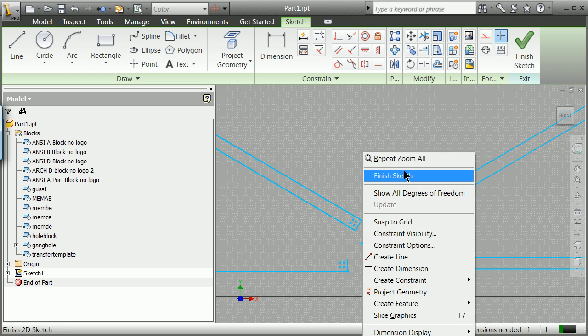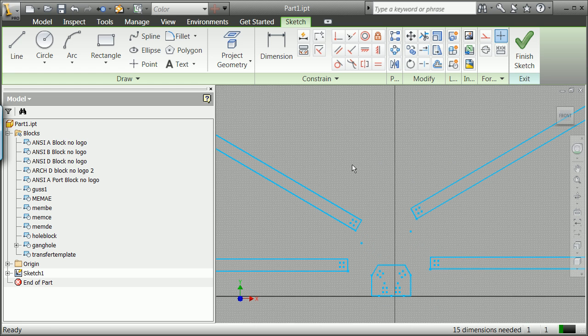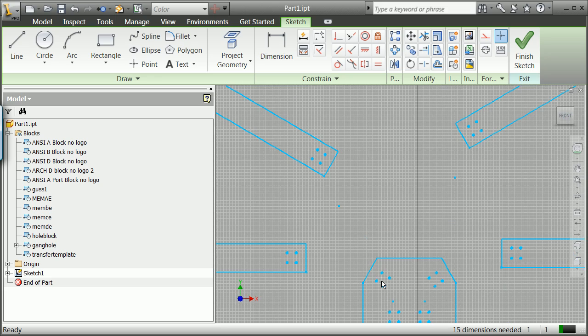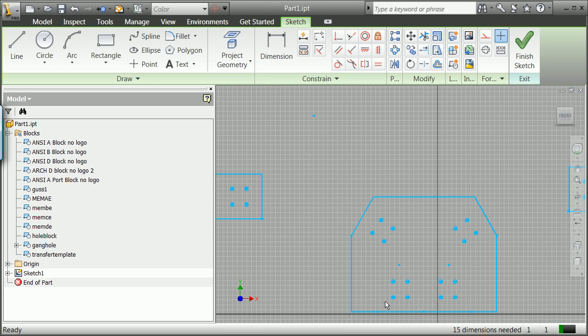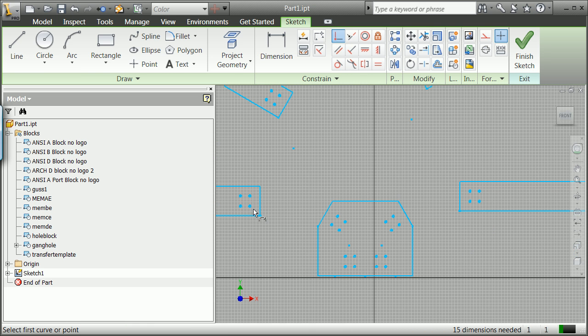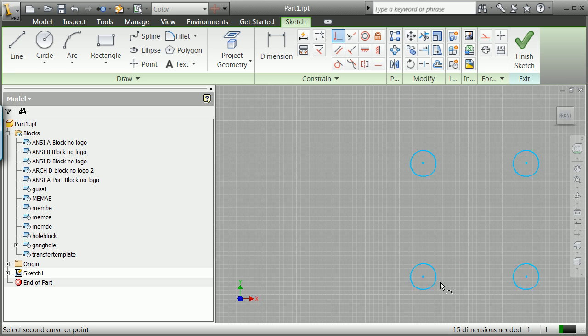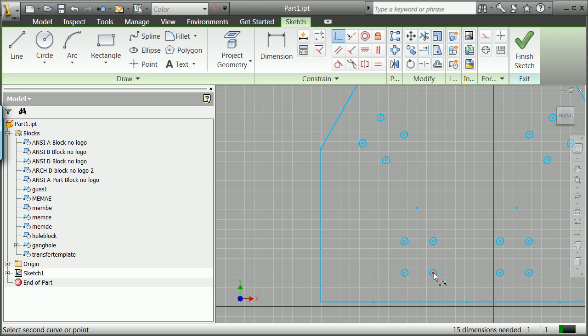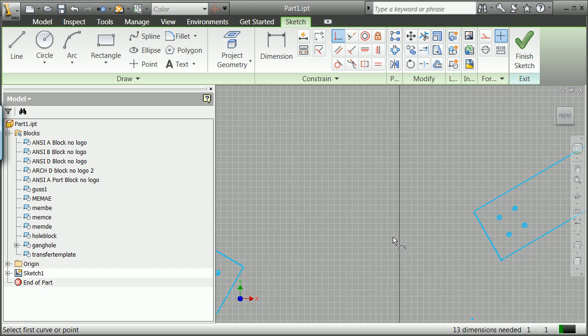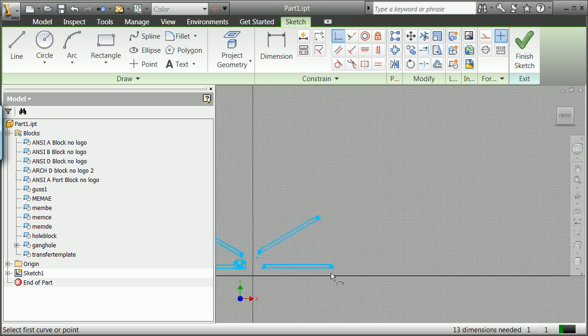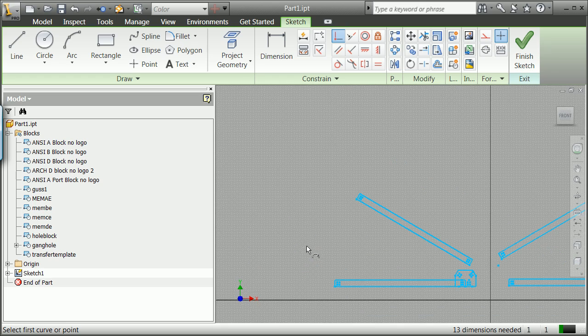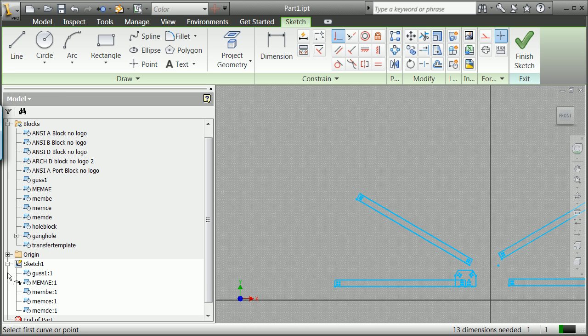And now we are at this point in the kind of sketch mode, and if you notice in this mode we've got these sketch blocks, and in this mode we can go ahead and get things lined up if we want. So you can do that by going to your constraints, and going to a constraint on that sketch block and telling it you want it to be constrained to this one there. It's going to pop it, and because we didn't lock one down or the other, it's going to move that thing there.